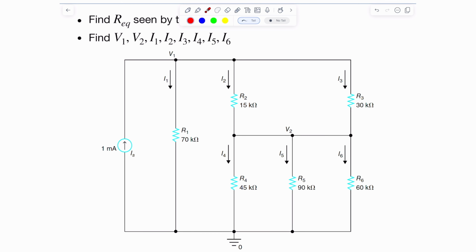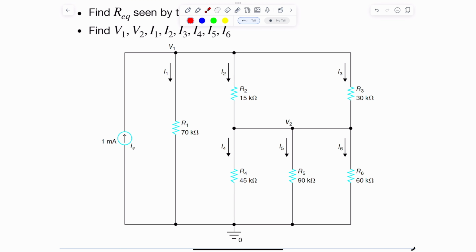Alright, so just before I continue, I just want to clarify what V1 is in here, because this is a little bit uncommon, or actually it's commonly used in circuit analysis. That'll become a lot more obvious when we cover nodal analysis. This particular notation tells me V1, but typically when we're associating a V, there's a plus and a minus, there are 2 points. When you see this notational convention, you will see somewhere there's some sort of a ground, or basically voltage 0.